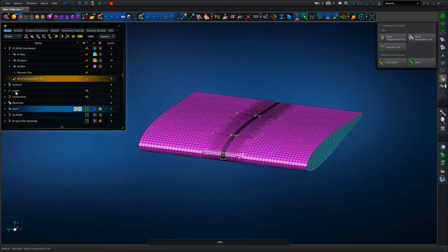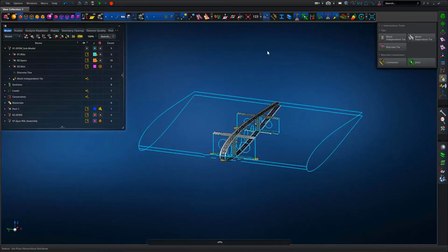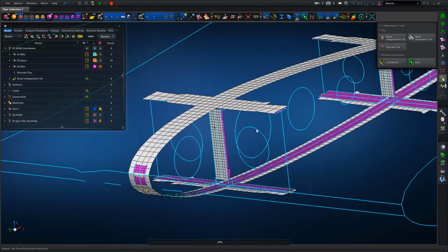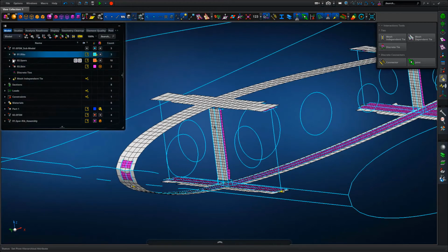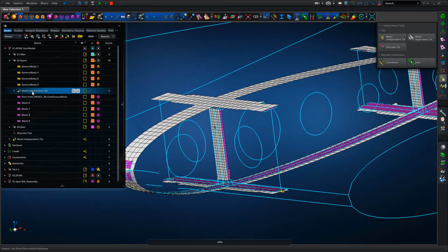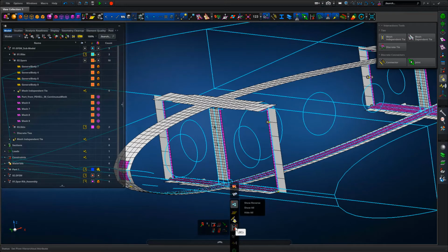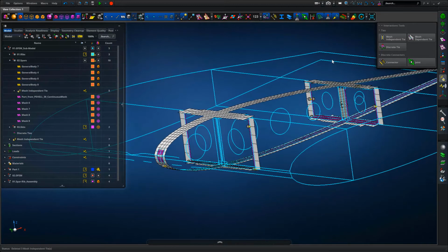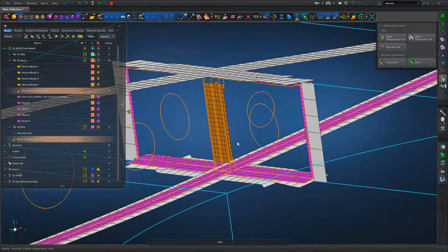So we can just double check those against the model that we've got. Okay, so got the glue contact in there. You can see, if you look closely, that we've got the spars glued into the ribs. We're going to delete those glue connections because we want to use a third submodeling connection approach here where we'll have explicit fasteners defined. So just deleting those glue contacts or the mesh independent ties at those interfaces.